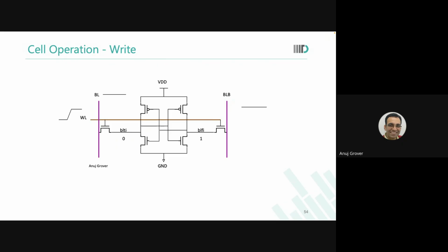So language is a conspiracy between two people, and we create those filters. We start to perceive things according to the words that are used. So while I'm calling this bitline and bitline bar, it does not necessarily mean that they are complements of each other. So the language you learned in DC, digital circuits or BE, that A and A bar are complements of each other, drop that language just yet.